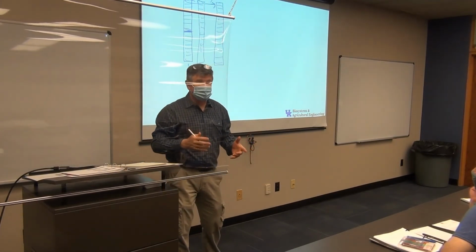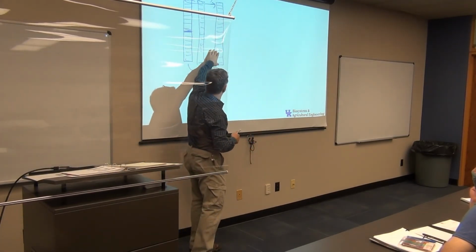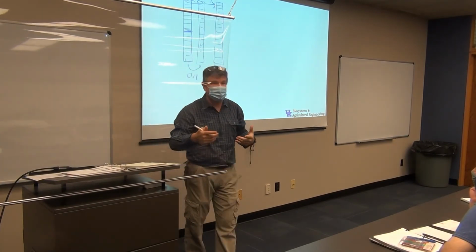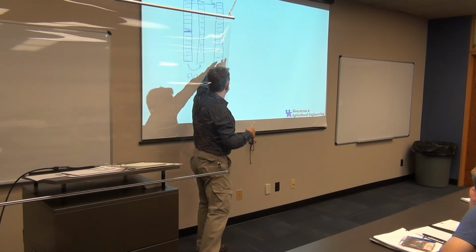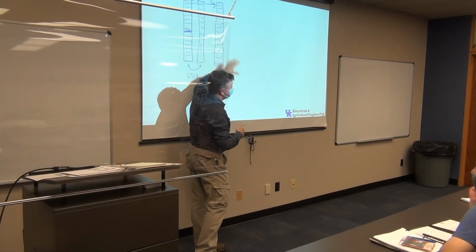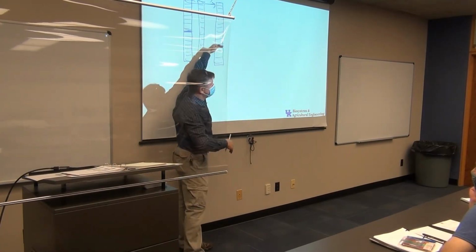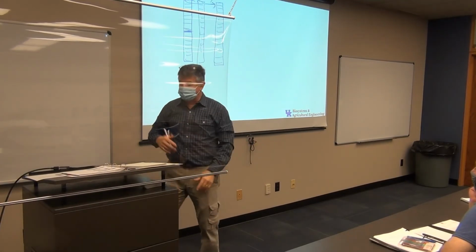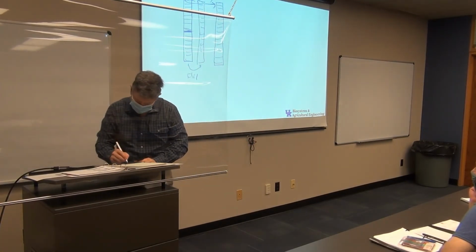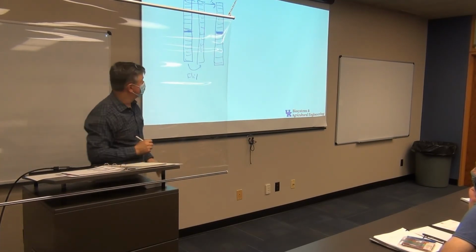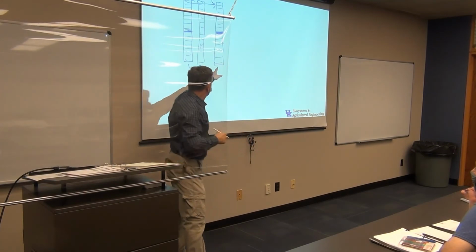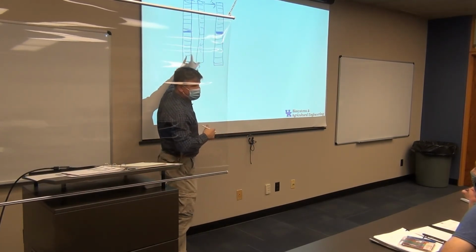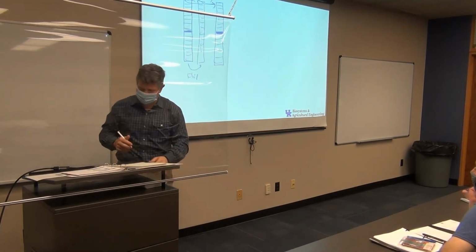So basically what I'm trying to do, this is not uniform. If I look at the uniformity of this, we calculate the CV. I showed you that in the videos. It's just a statistical thing, standard deviation divided by the average. It's the coefficient of variation. The coefficient of variation on that would not be good. So what I need to do, and this is the center nozzle, you've got to keep track of where that center nozzle is, where the nozzle is in the center of the pattern. It's not always right in the center of the pattern. It will be here now, but it may not be here. So keep track of where that nozzle actually is.